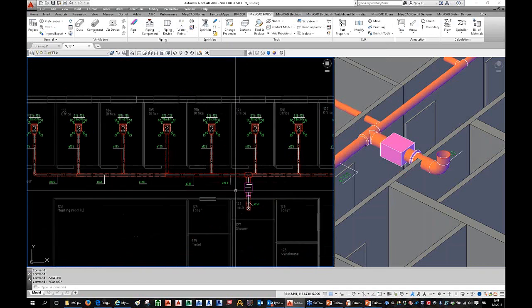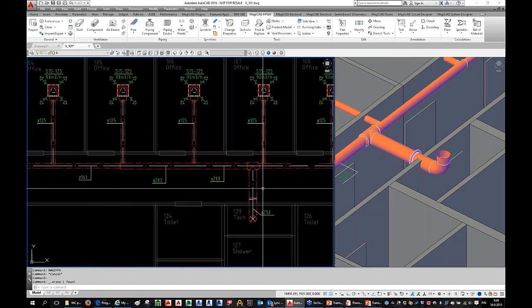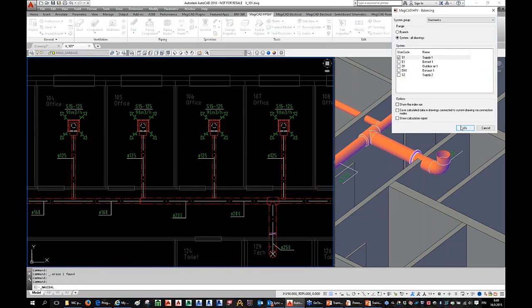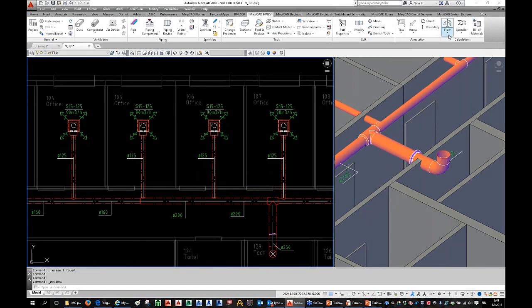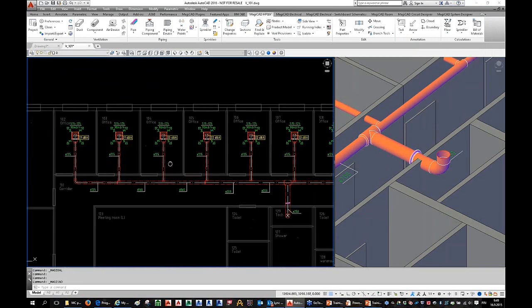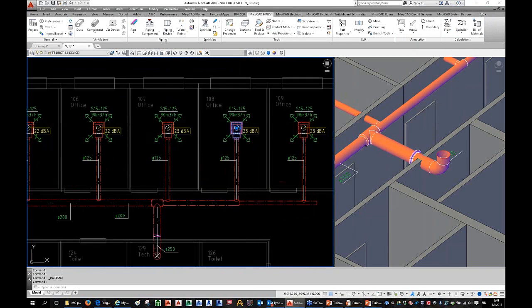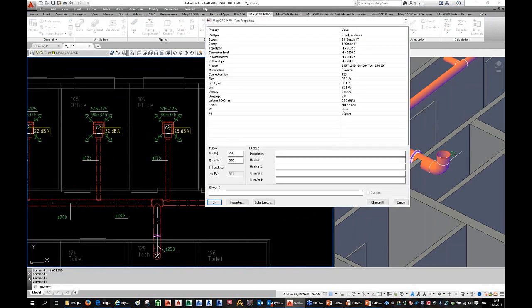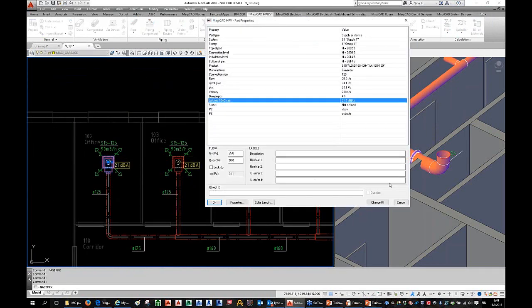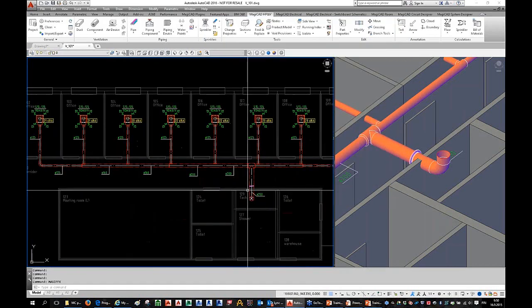And if I, for example, take this silencer off of my network now, and again I run the balancing because the pressure drop is changing, and then I run the sound calculation, you can see that it might affect some devices. It depends what kind of silencer you are using. It didn't affect much, but a little. This was 20.9, now it's 21.2.